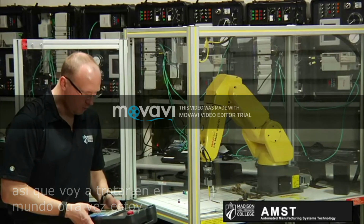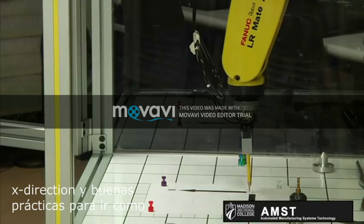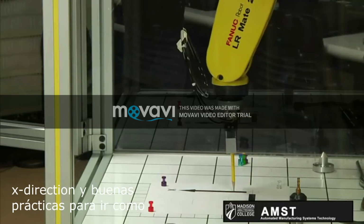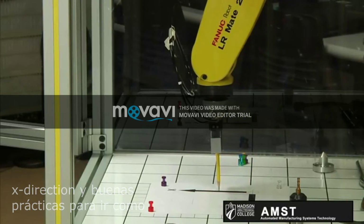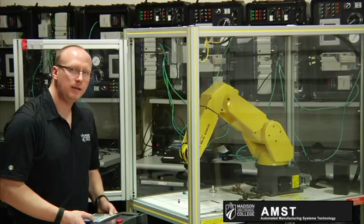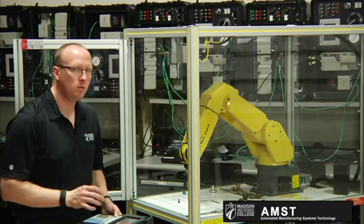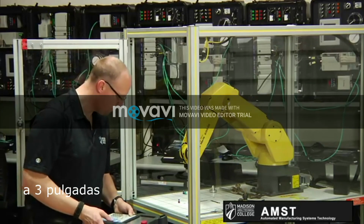So I'm going to jog in world again. I'm going to go down the positive X direction. And good practice is to go as far as you can. The larger you create the axis, the more accurate it's going to be. But at minimum, you should move probably 2 to 3 inches.